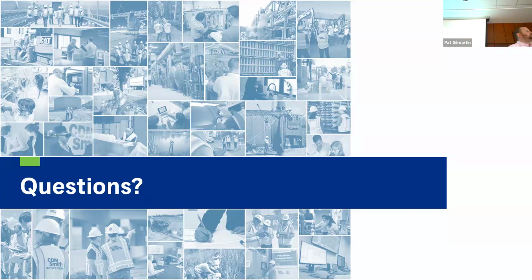Example, kind of where there's wooden piles. Well, wooden piles wouldn't necessarily stop the drill. They could drill through it. It's not as great as one, it could potentially clog your drill head, causing issues. Two, they could potentially put like a rock bit or something on to get through it if they're having trouble with the main soil bit. But ultimately for us, we just wanted to avoid having any issues with a true obstruction.